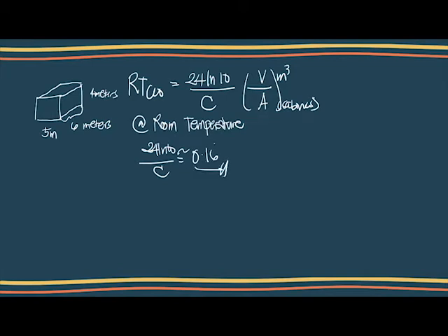That is why in some books, it is directly substituted as 0.16 multiplied by V over A. Then we can find the reverberation time RT60. This is what we call the Sabine formula.